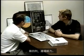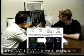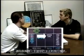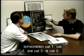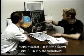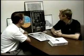Fourth column, approach capabilities. We have Cat 1, Cat 2, and Cat 3, and then you have on your second line a single and a dual. Explain to me the modes that we get on the Airbus. Okay, we only get four really. We get Cat 1, Cat 2 alone, or Cat 3 single, Cat 3 dual. We'll never get Cat 3 without a single or dual, and we'll never see single or dual associated with Cat 1 or Cat 2.